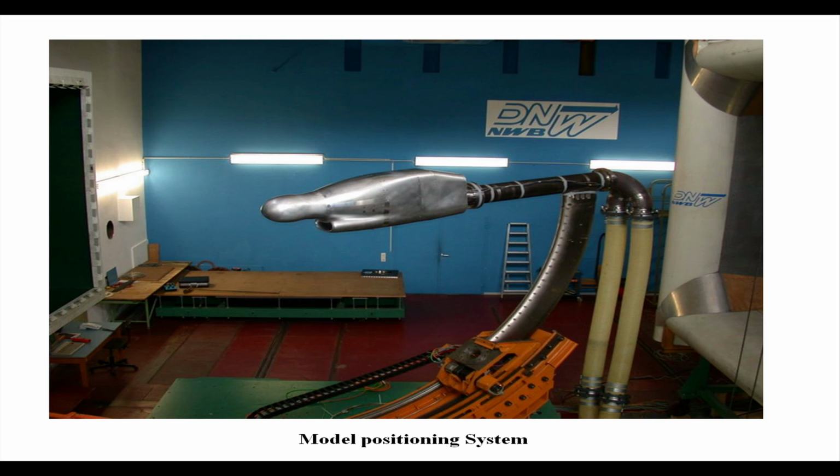Again, the model positioning system with all its instrumentation should remain very rigid when the flow moves past it with the model attached. That's another very major requirement. Otherwise, the system may start vibrating, may even get excited at different frequencies, and those are going to affect your results finally.